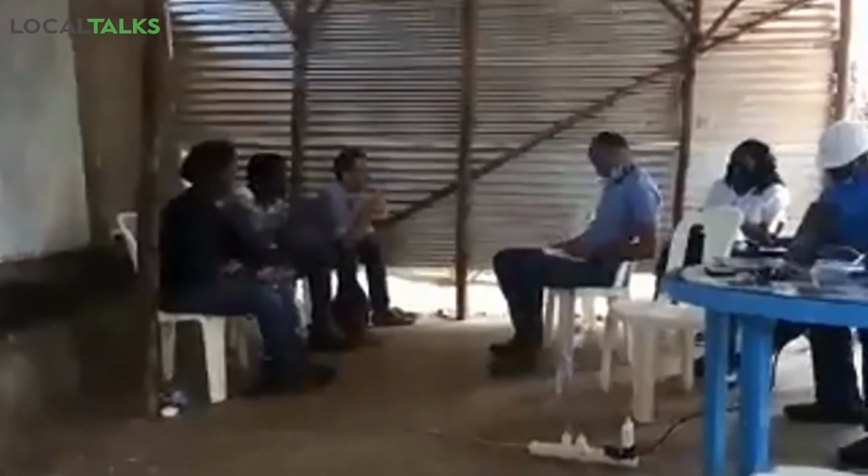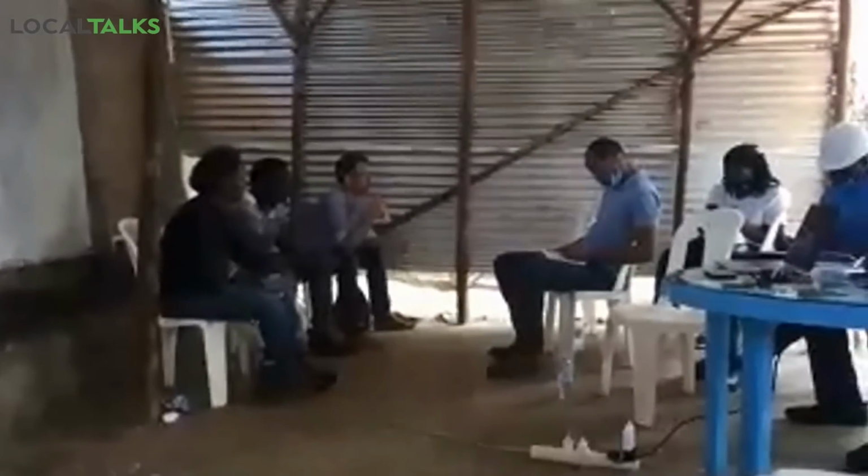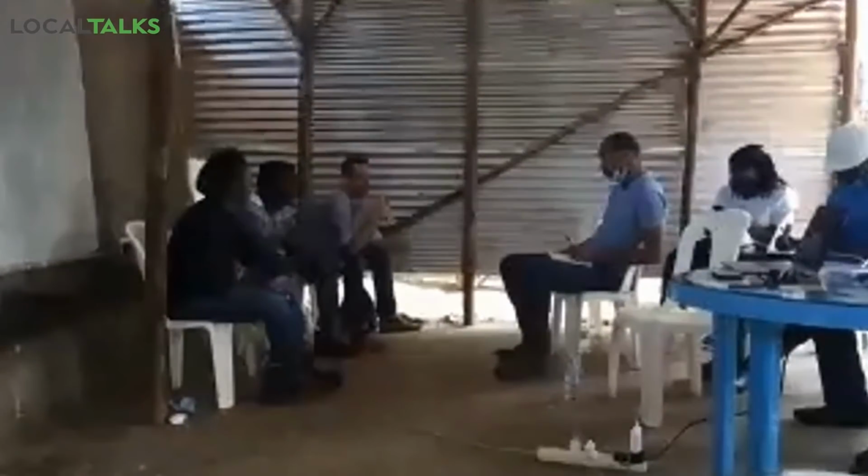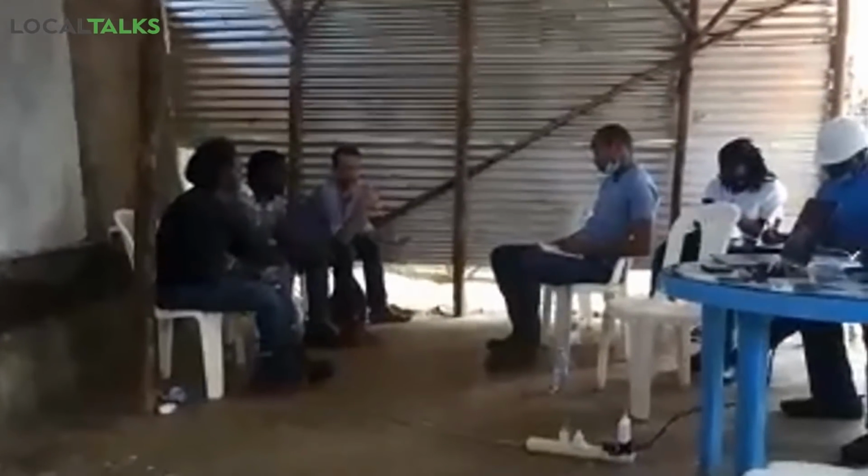One thing that will require maintenance over time is the lime earth plaster. Now that is exactly its strength. The strength of earth-based plasters is that they can be very, very easily repaired, improved, patched up over time. That's one of the big differences to cement-based painted plasters or chemically enhanced plasters. It is impossible to patch that up very well over time, whereas the earth-based plasters are really, really good at that.